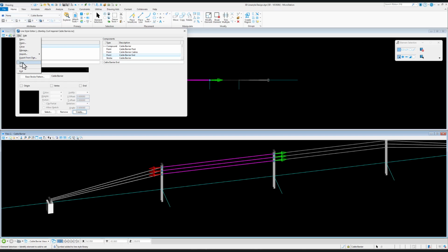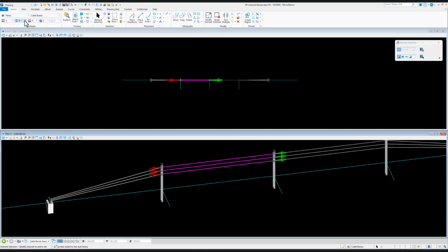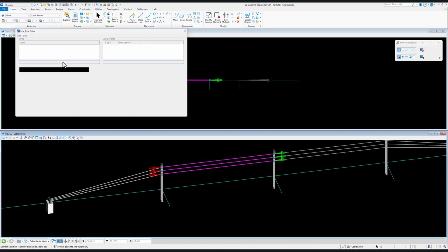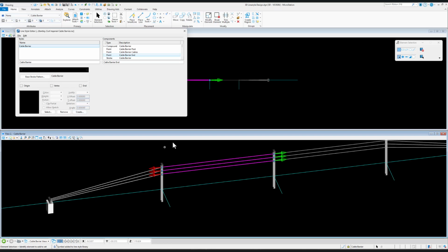Again, we will save, close, and exit, just like we were doing before, and then reopen the file. And again, just go back into the point section. We actually don't need to change our insertion point now. We still have our insertion point set here for the cables. We'll have the same insertion point for the post and for the end.